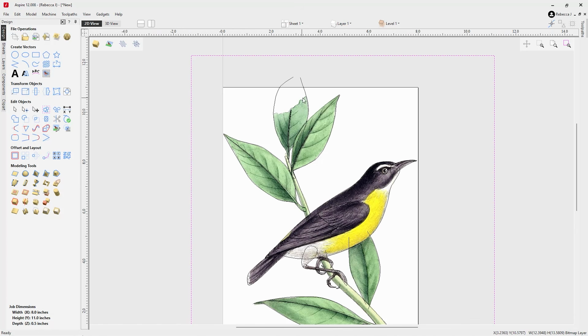Okay, so this leaf obviously has been eaten away by a very hungry caterpillar, and so when you're creating models where you kind of cut things away, the best way to do it is to actually create the model as if it was fully there, which is why I've drawn these rails here. I intend to create a full leaf, but then what I'm going to do is create a shape where we're essentially going to cookie cut it out.